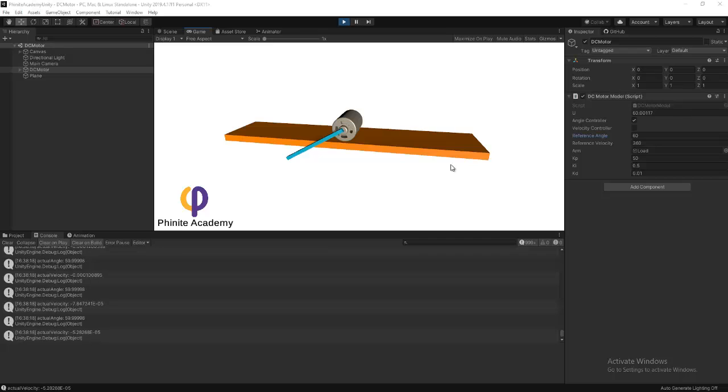But especially in the discrete form application, we should design a discrete PID controller, okay? Because Unity is a sampling program, which means the sampling period is 0.02. We need to create a model via the physics motor, representing the whole DC motor model, and we should implement the specific controller based on the PID parameters. Especially, we should implement a discrete controller design, okay?